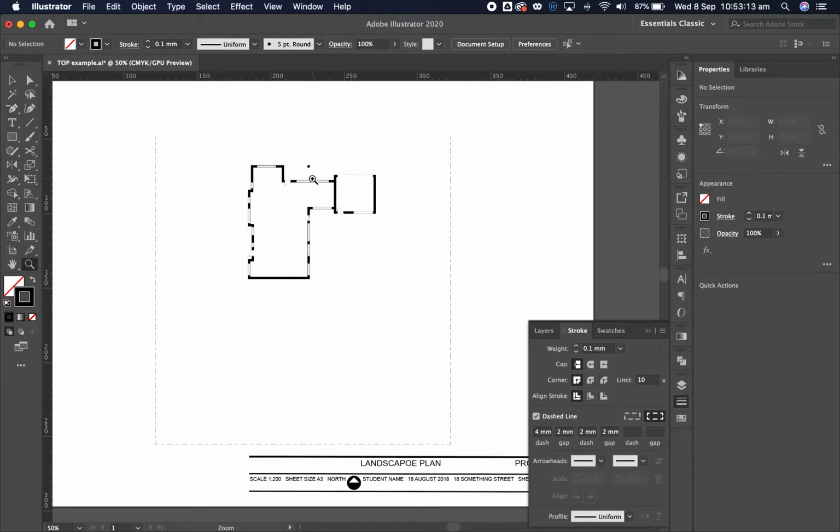All right, so as default, I like to have my increments as being 500 mil increments. If you go less than 500 mil increments, then that's half a meter. You will run into some problems with basic sort of slight increments in terms of sloping things. You could bring it down to 250 mil, but I reckon that'd be the absolute bare minimum. All right, so let's move on.